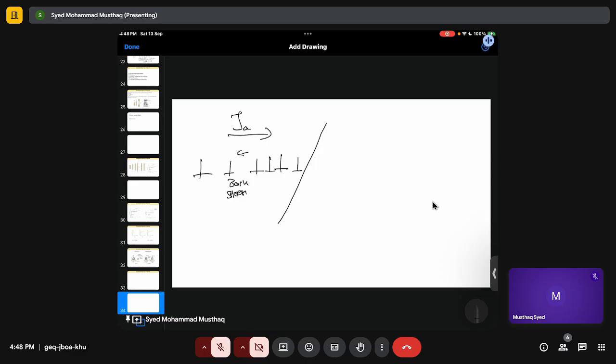And this stress will be resolved. Whenever a stress is applied on a surface, it gets resolved, so you will have a resolved shear stress. Let's say the number of dislocations is n, and tau c will be the critical stress required to initiate dislocation motion, or move dislocations from one grain to another grain. This is called the critical shear stress.